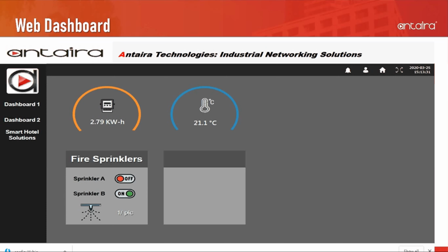If there's a fire in a building, and if the water pressure drops below the predetermined level, then the fire pump will be switched on to make sure that the water from the water tank can be pumped into the hydrant pipes in order to extinguish the fire via sprinklers.